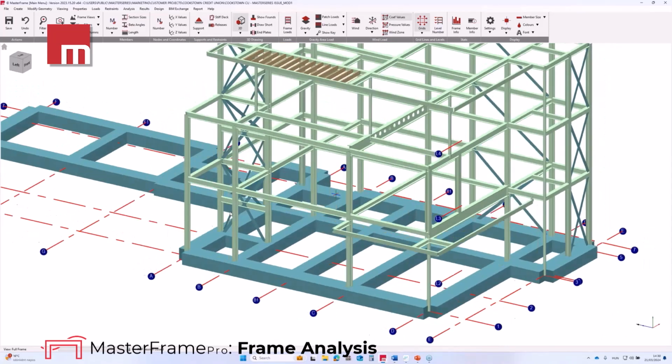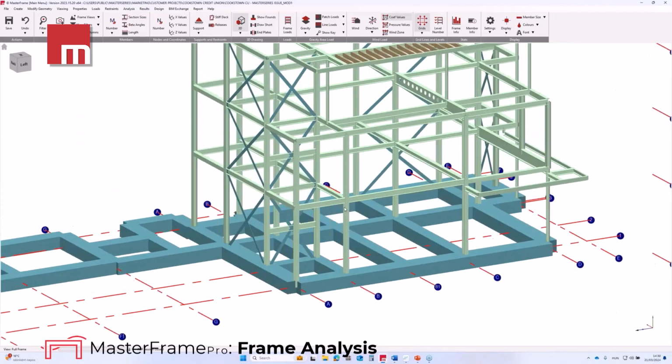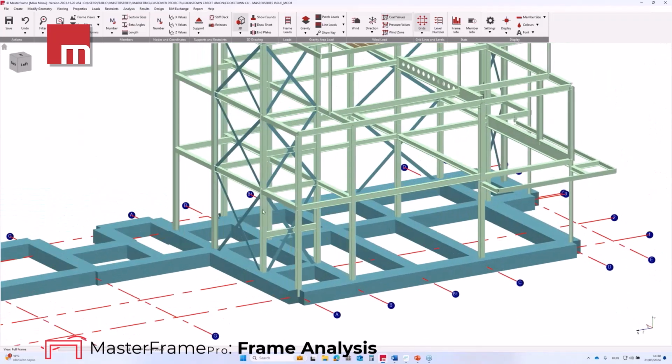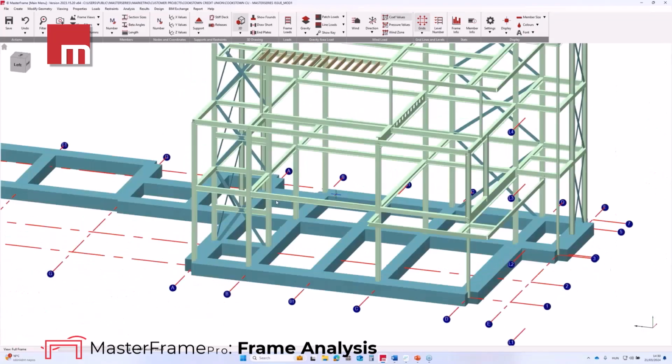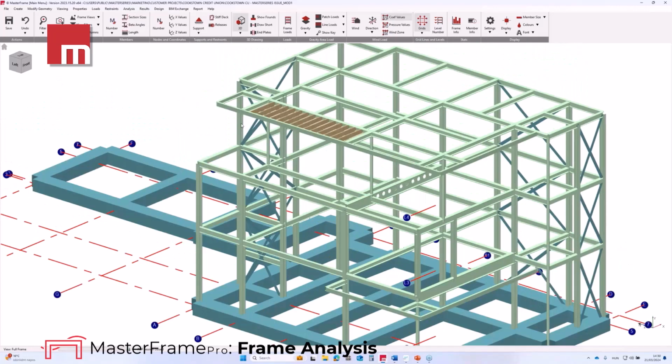We have vertical X braces in both directions as well, here around the staircase and around the opposite corner. This bracing system provides lateral stability for the building. The bracing members are tension-only steel flat bars. Timber joist beams on the roof were not part of the original model. They were designed separately. However, I added some of them to present that it is possible to analyze and design